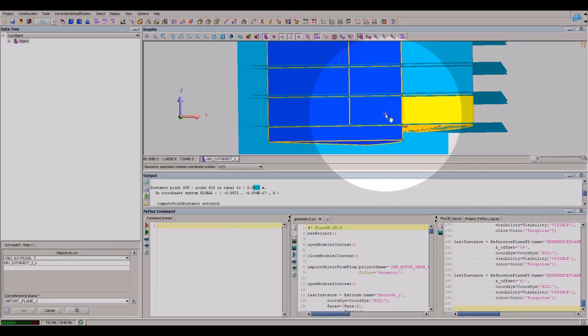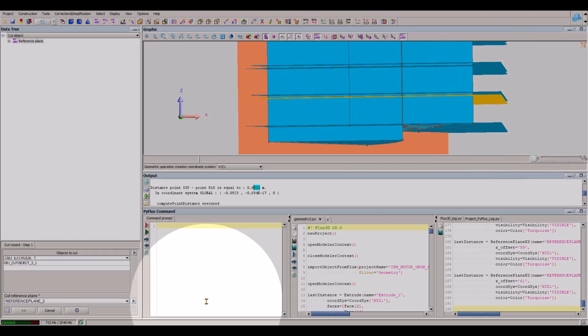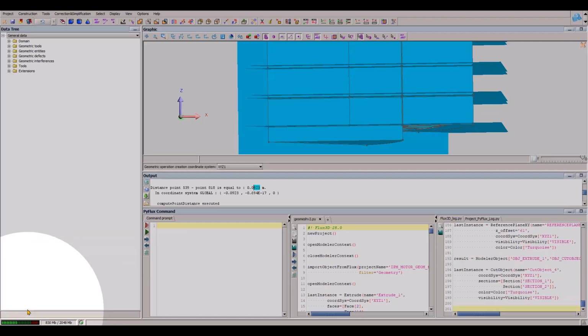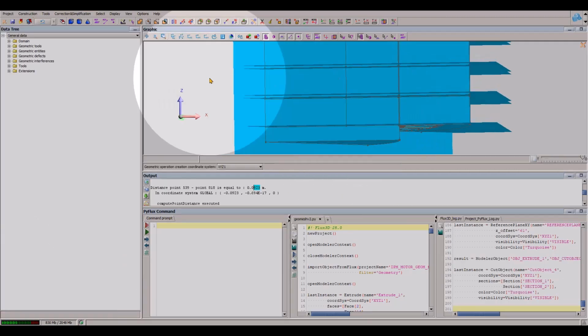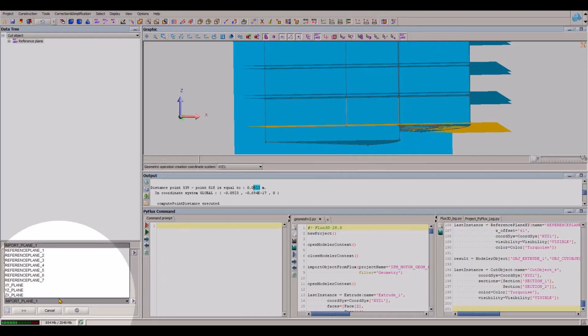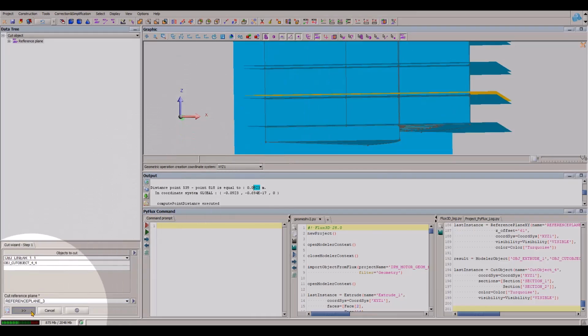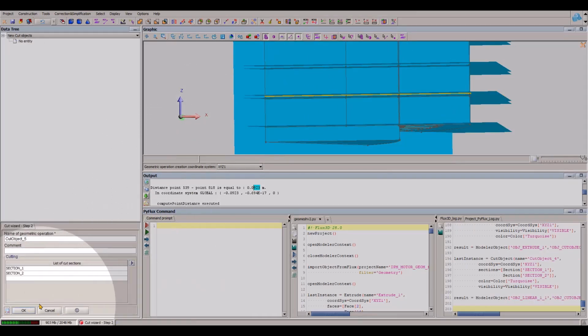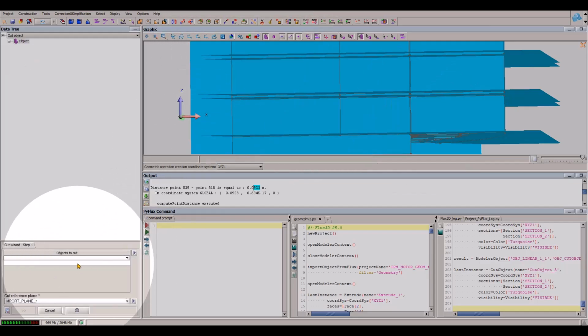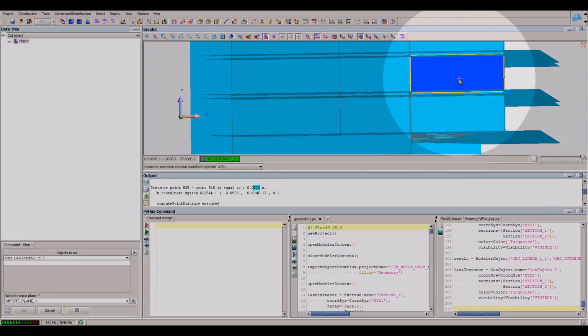Later on I will have intermediate layers I will mesh with extrusive mesh, and then the junction layer will be tetra mesh. Like this I can optimize the mesh as I want, and I will not have any issue making a mapping between the extrusive mesh and the tetra mesh.